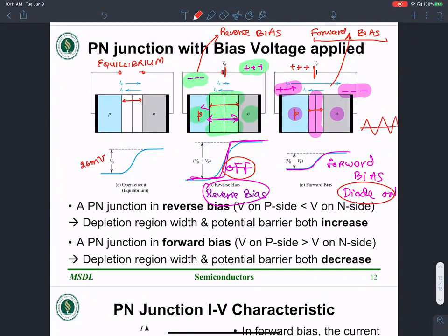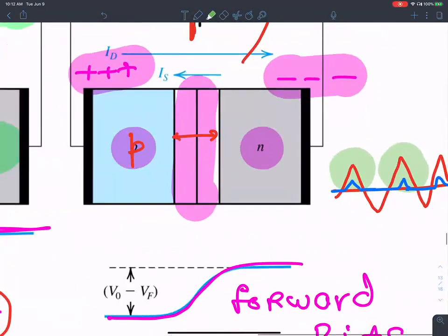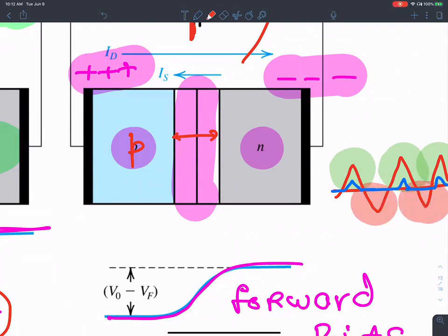when you had a triangular wave in the input, the output was only active for certain duration. Okay, the rest of the wave just did not pass through. That's because during the positive half cycle, when the input was positive, during the upper half of the cycle, the diode was forward biased, and then it let the input voltage pass through. On the other hand, down below, where the input polarity was negative, the diode was reverse biased and it did not let the current flow through. This is what you saw in the earlier labs.